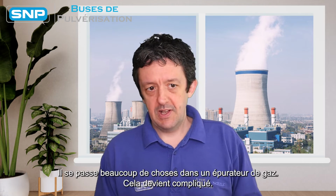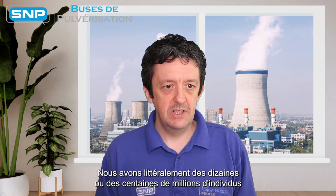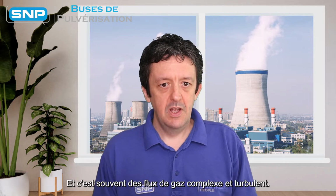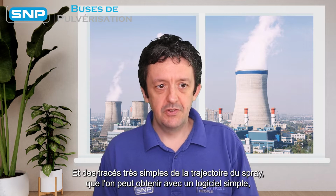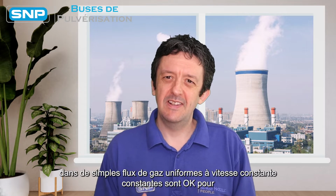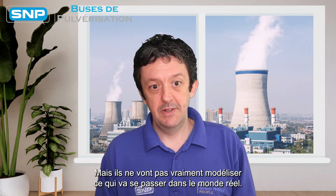Now, a lot goes on in a gas scrubber. It gets complicated. We have literally tens or hundreds of millions of individual drops of varying sizes moving around, and it's often complex and turbulent gas flows. It's a complicated system. Very simple spray trajectory plots, which we can get from simple software, into simple uniform gas flows at constant speeds are okay for testing very basic assumptions, but they won't truly model what's going to happen in the real world.